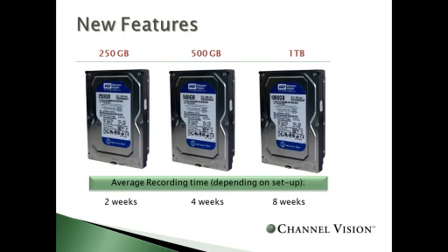A question we often get is storage capacity and how much do I need? This is another question that has a lot of variables, including your frames per second, the resolution that you're setting at, the compression that you're using. So there is no real specific answer to that, but to give you a ballpark idea, using an average resolution on your setting with an average frames per second, you could expect to get about 4 weeks of recording on a 4-channel with a 500 gig hard drive.